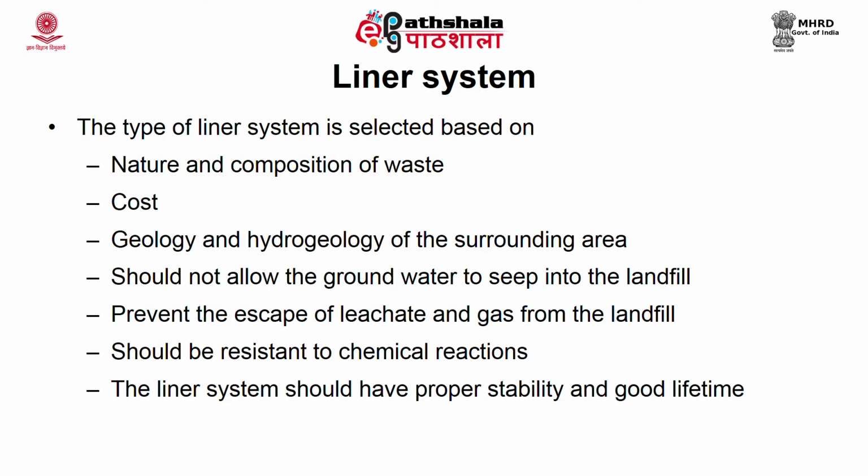Then it should have proper stability and good lifetime, because once you construct a landfill, it will go for a design period of 30 to 50 years. Even once you line the system and start loading the waste, it is difficult to remove it again if there is any problem, if it is not stable and if there is any leakage. It is difficult for us to remove and then replace it. So, while selecting or layering the liner system, you have to take proper care and attention to choose a stable liner system which is of good lifetime.